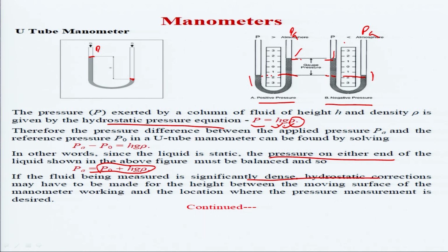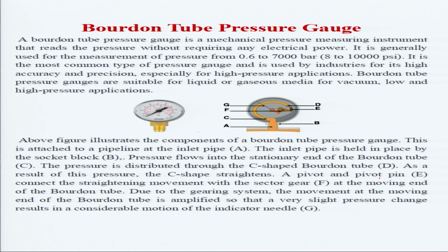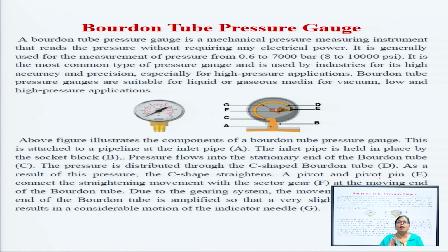We can directly measure the pressure with the help of this. Again, this is a very important parameter. We are using the Bourdon tube pressure gauge. The Bourdon tube pressure gauge is the general type you have seen in your homes, colleges, offices, and any lines: pipelines, water lines, gas lines. They are using the C-type Bourdon tube.